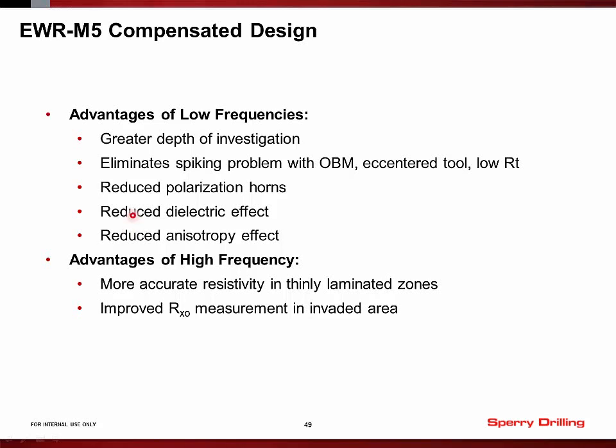Another couple of benefits. One is reduced dielectric effects. The formation resistivity is only one property that the formation has that this tool is affected by, the other being the dielectric properties of the rock. The advantage of using a low frequency is that the dielectric effect is much less, and the resistivity is the predominant mechanism that controls the measurement. So in some cases where we have formations with unusually high dielectric properties, using a low frequency measurement can help.